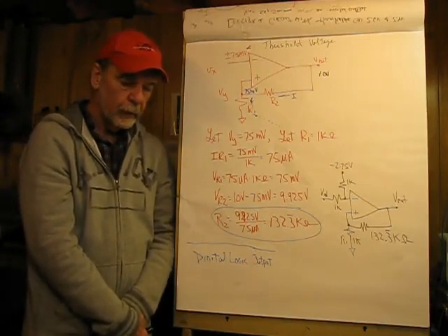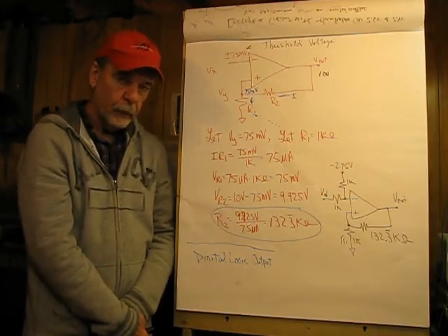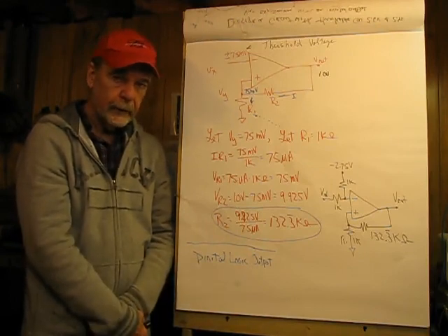So if you're doing problems on this, take your time, think it through. The positive input's more positive than the negative. The output's going to be high, and that should be your guiding light.